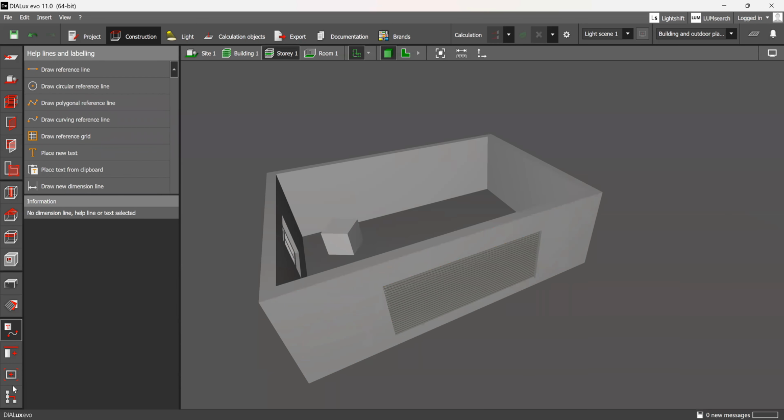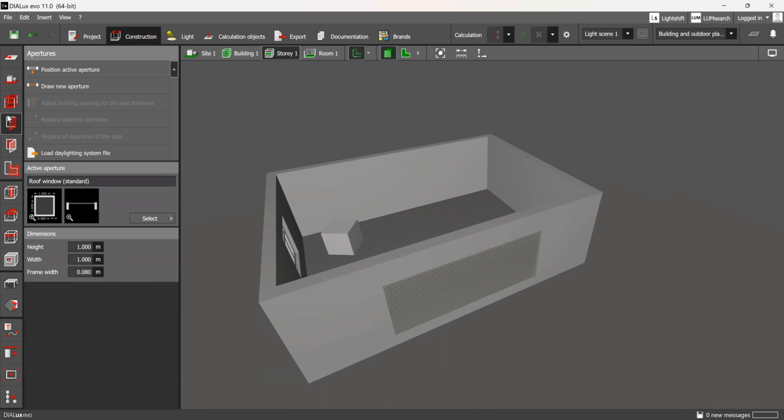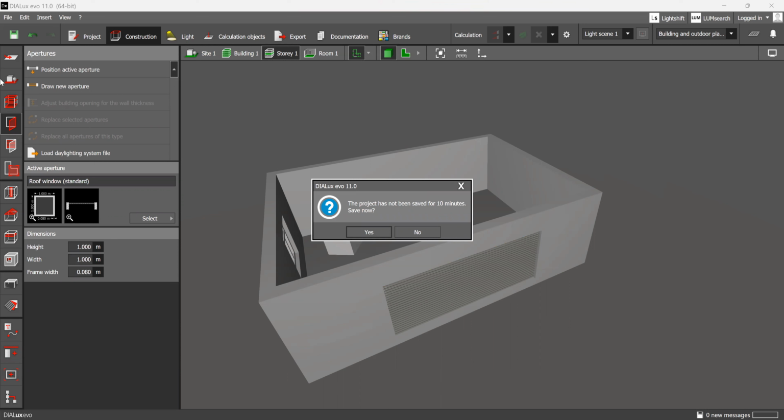And the rest of it, these last four, are what we call guiding lines in architectural tools, or they call it something else in this tool. They are used just to pinpoint things in the simulation tool. They're not actually used for any calculations, they just give you coordinates of where to place other things. So the important parts for the simulation are the site where we draw the building, the windows, and the blinds. That's all you need to remember. The rest was extra components for your information. Just remember three things: site, window, and the shades.